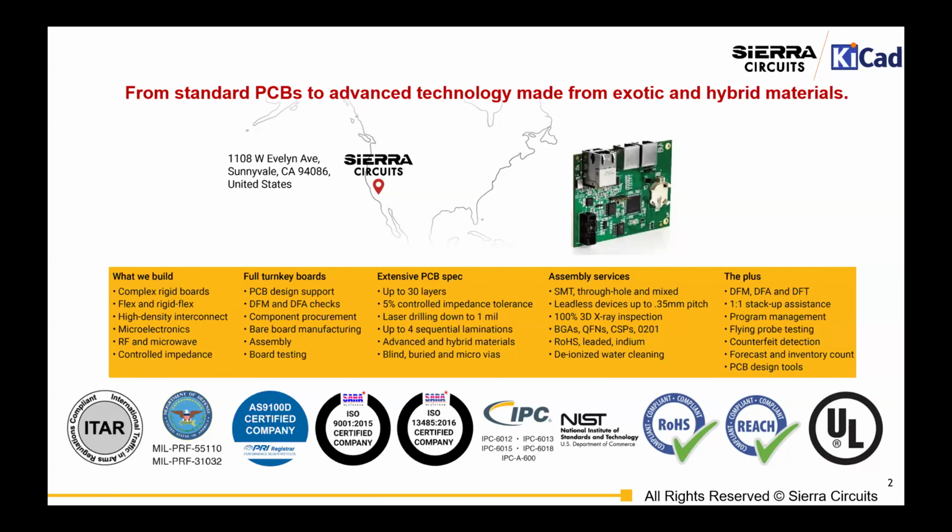Yeah, absolutely. So one more common scenario is that same thing. It's an SMD pad, so a surface mount pad with a surface mount device and a drill hole inside the pad. Whether you're going to plate or not, I guess doesn't matter. Right, well, that's I think exactly what they were looking for there. You have a non-plated through hole. It's basically a drill hit on that pad.